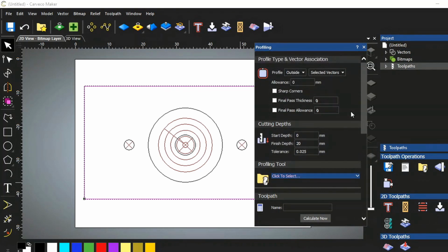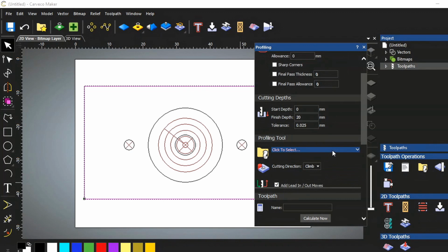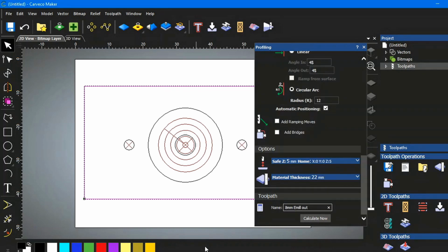I'm just running back over, checking to see that I've got all this right, because you can end up machining into the jaw of your vice if you're not careful. So maximum depth 20 millimeters. I know I'm going to be gripping on the last 3 millimeters, so that means I'm going to be clear over the top of the vice by 2 millimeters at the end of the cut. Yep, that's fine. Okay.